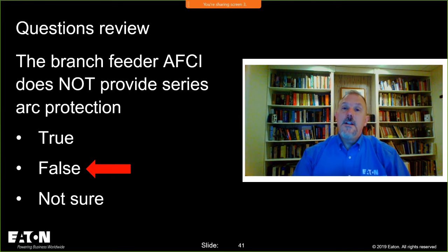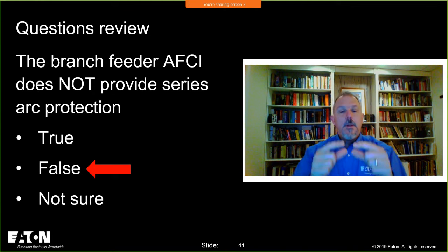Those devices are rated at 120 volts. The moment you put a handle tie on two circuit breakers that are rated for 120 volts, you are now applying those two breakers at 240 volts together. And that is ungood.